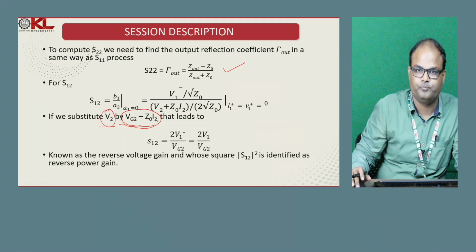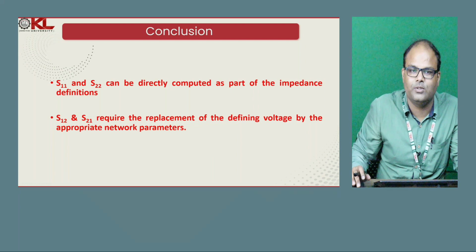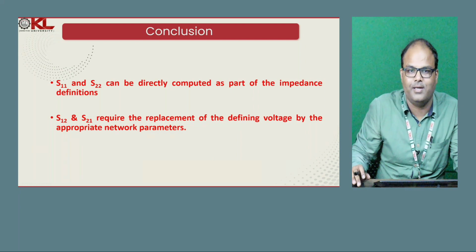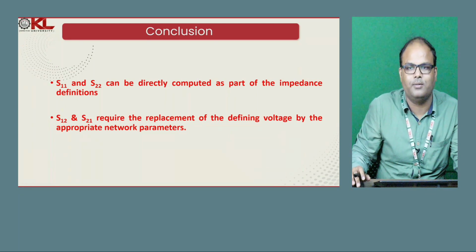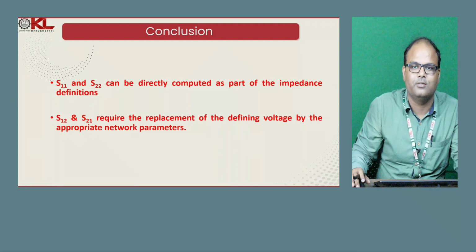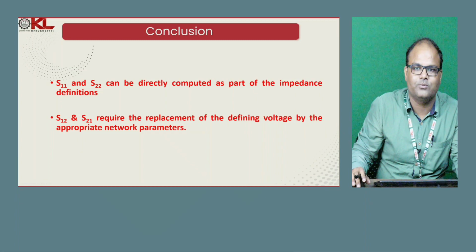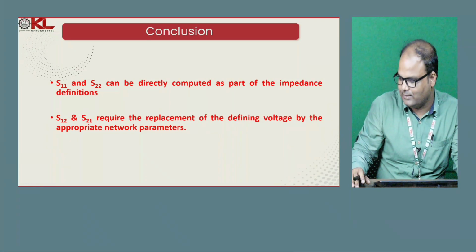Now from this we conclude that S11 and S22 can be directly computed as part of the impedance definition, and S12 and S21 require the replacement of the defining voltage by the appropriate network parameter. So we can think about two things, one this side, one that side.